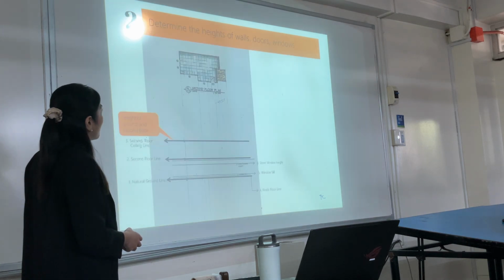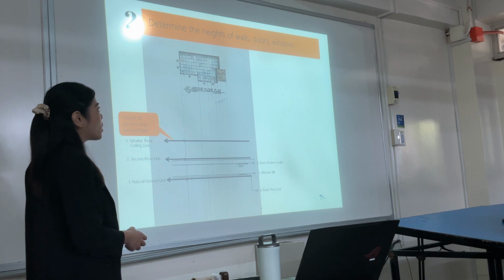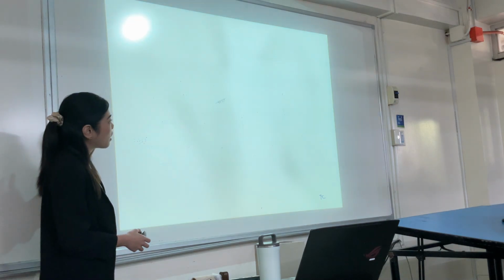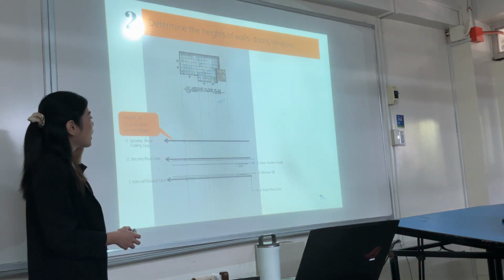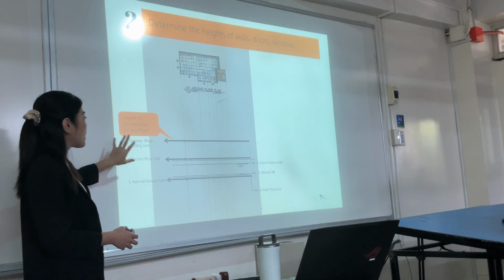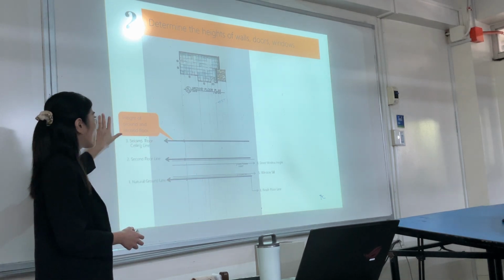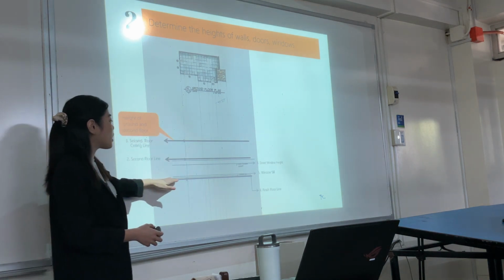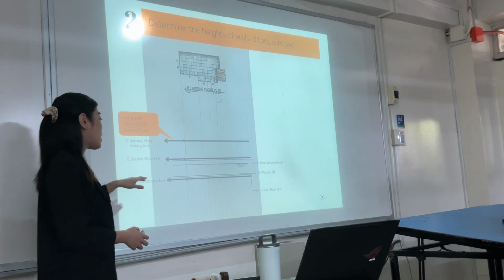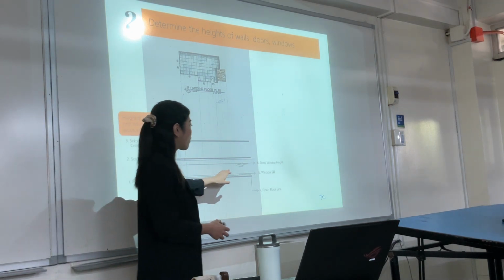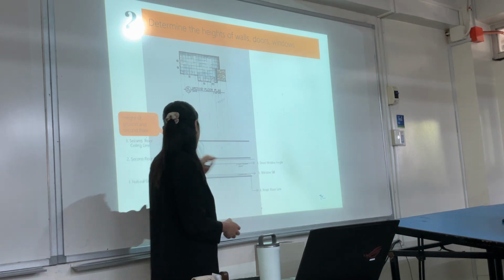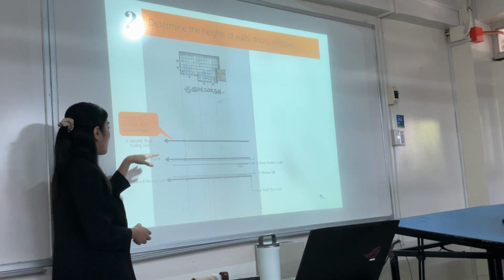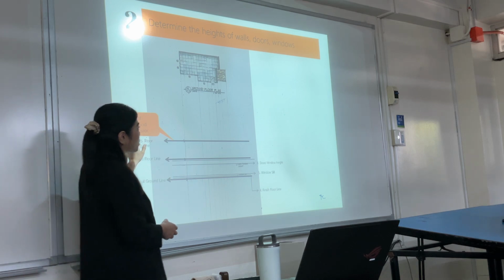So, step 2, determine the height of walls, doors, and windows. So, these heights are just guidelines na yan. But this floor level, ceiling height, dapat mapakita nyo siya. So, height of ground and second floor, you have 3 main. So, you have natural ground line, pero pwede mo yun siya i-shortcut into NGL. You have ground floor finish line, or FFL. And then, you have second floor line. So, second FFL din yan siya. Third, second floor ceiling line, ma-shortcut mo din yan siya to CL.